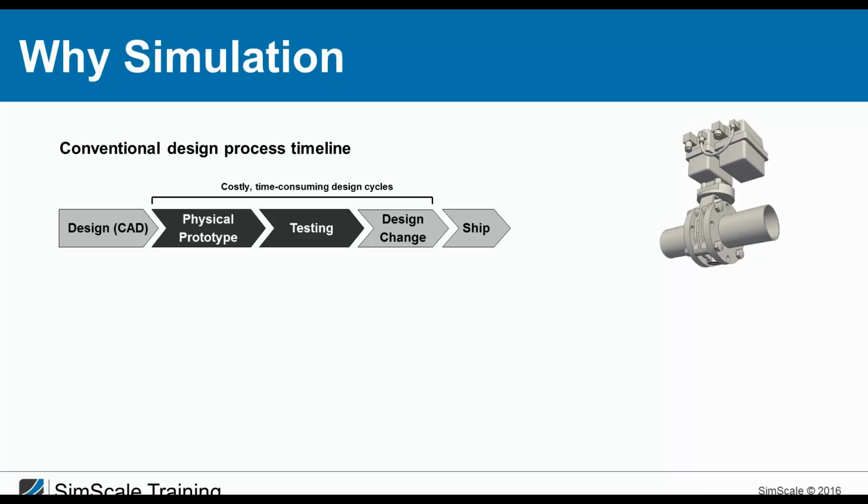And usually you will get a list of requirements from your supervisor or from the client, saying, for example, when we talk about the valve, we need this diameter for the valve, we want to have this mass flow through the valve, and we want to have maybe maximum this pressure drop. And basically, the main function of the valve, opening and closing a hydraulic circuit, is delivered by a valve body, which is inside this outer shape, this housing of the valve, and which can open and close the cross-section.